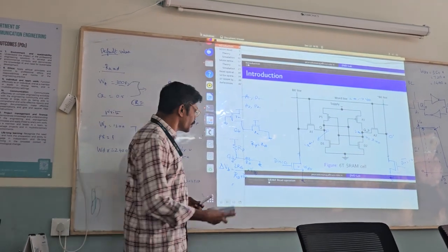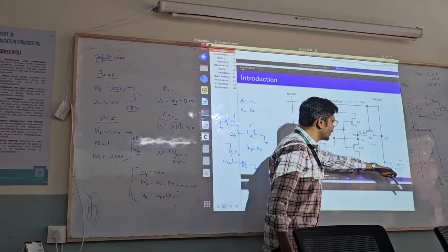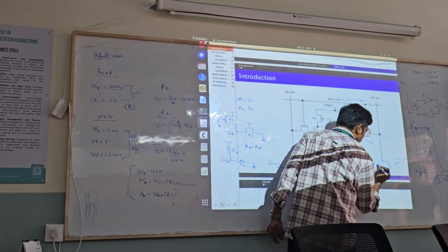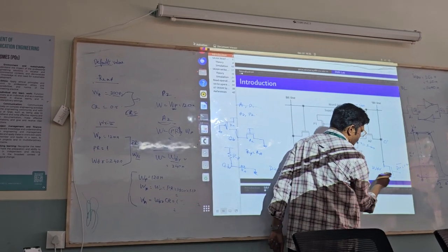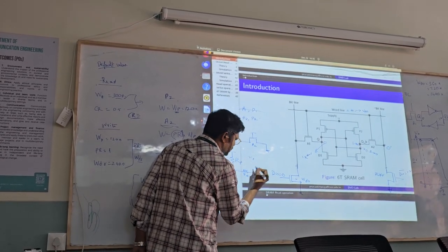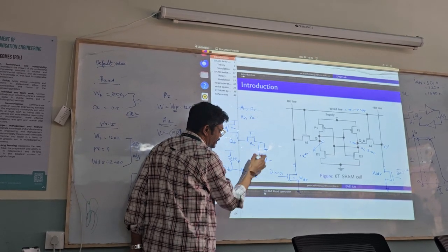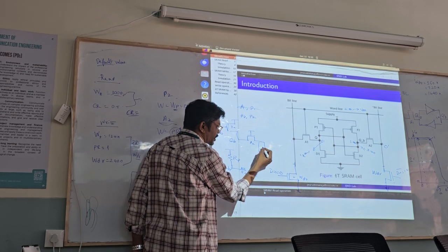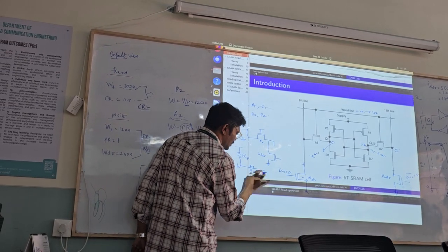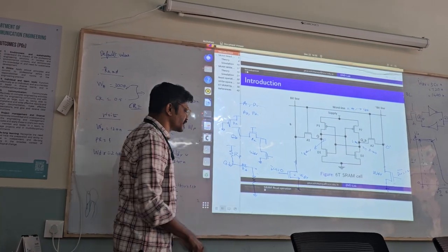Now, what we do next is, during this discussion, we have not included this guy. Why is this guy more important, the driver? Because of this input, this particular transistor will be on, and that in turn will create an additional resistance. So we have a resistance, and this node is not actually connected directly to the ground, but rather through this driver, it is connected to the ground. So this means I have some resistance followed by which the ground is connected.